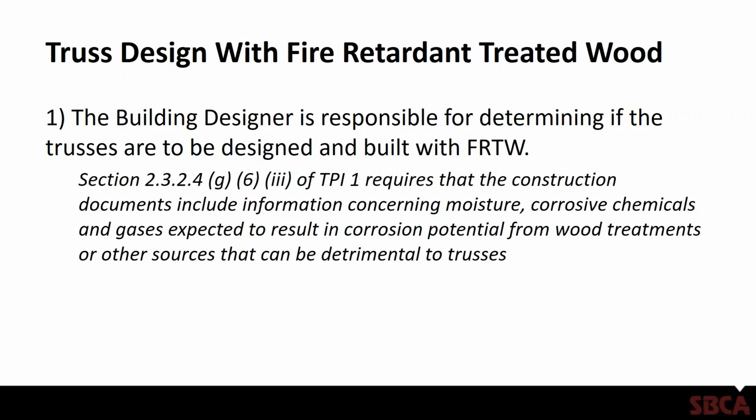So, specific to trusses, if a job is specified that requires fire retardant treated lumber to be used in the trusses, the building designer is responsible for determining if the trusses need to be designed and built with fire retardant treated wood.